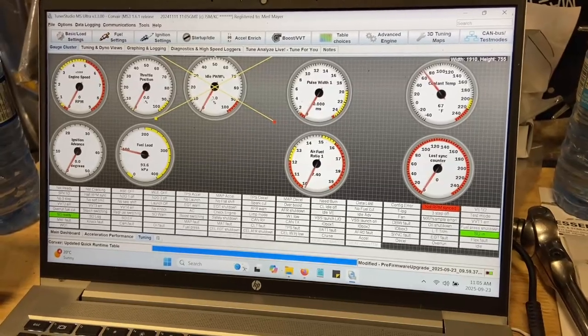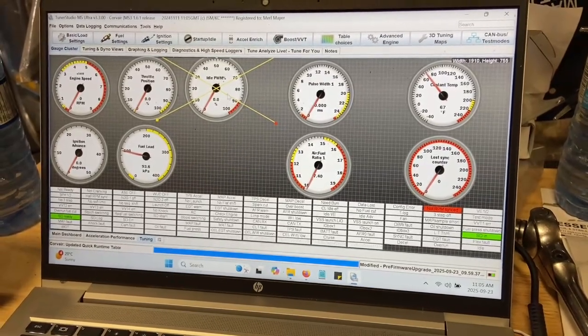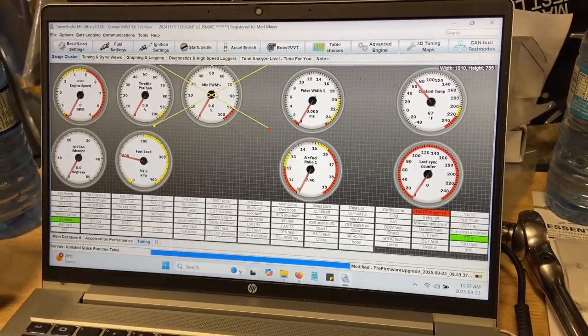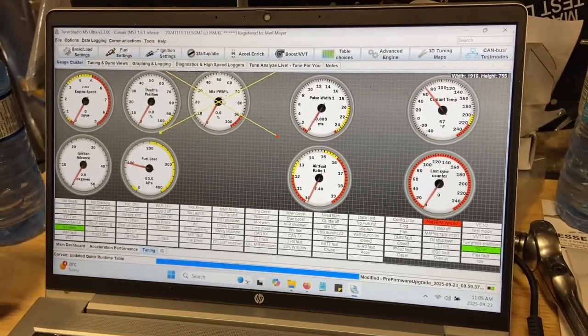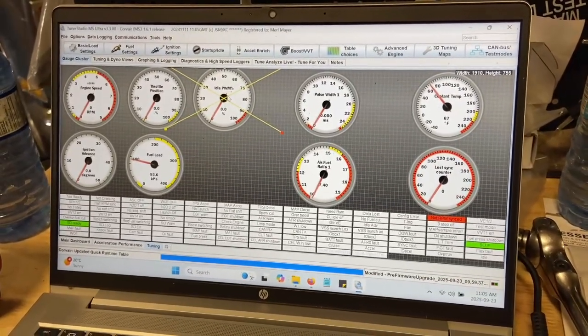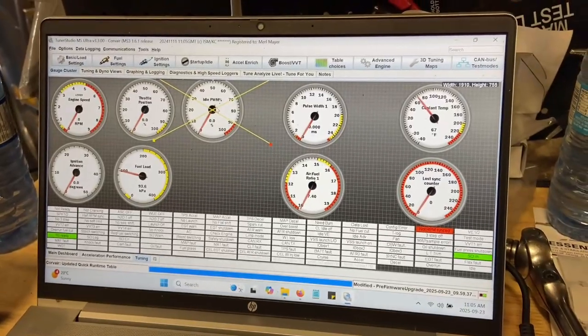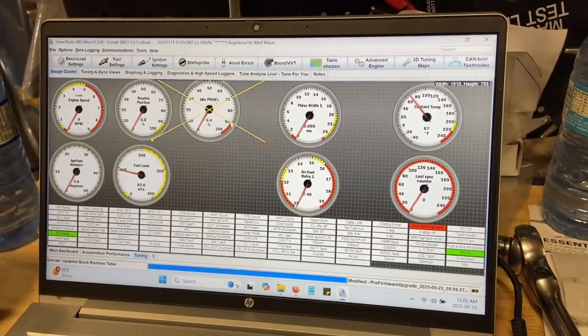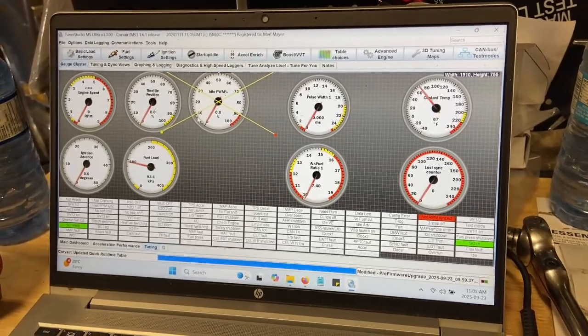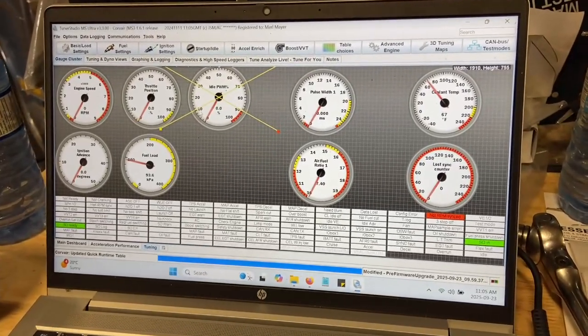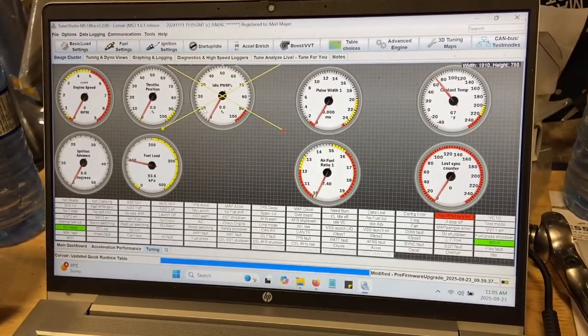So this tells me what pulse width my idle valve is. That's going to help me set up my idle valve, so when I am opening and closing the throttle plate with the screw, I can get it dialed in where I have a lot of range for high idle, and for my low idle, with the screw set, I want that to be at a fairly low percentage.